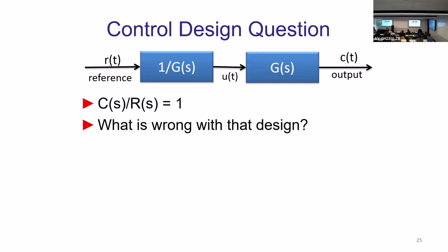Oh. Why not? In that case, you are measuring the output of system G, like the motor is already rotating, doing whatever, and you're measuring, and C equals R. We're not controlling anything, is it? Just an input. Of course, you control it. You're sending input signal U, which is the control effort, by that controller from your reference input, such that your C will try to mimic whatever R is doing, because this is the inverse dynamics of G of S. I inverted the dynamics, pulling it through, to get to the second one.